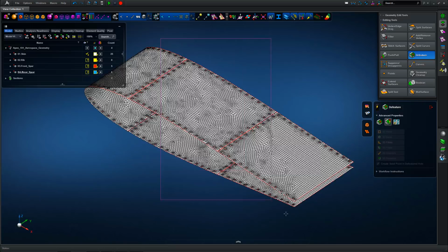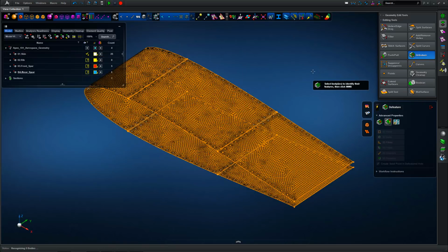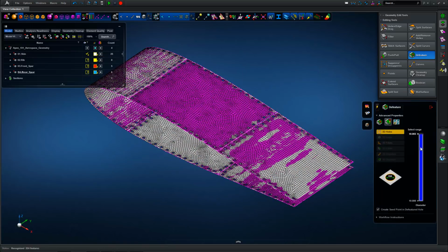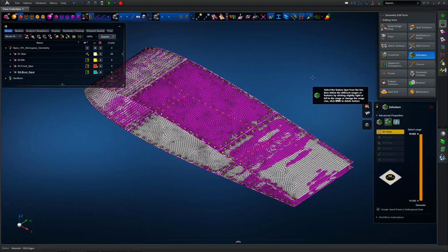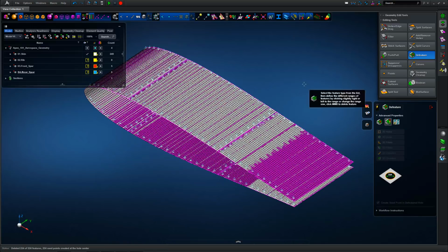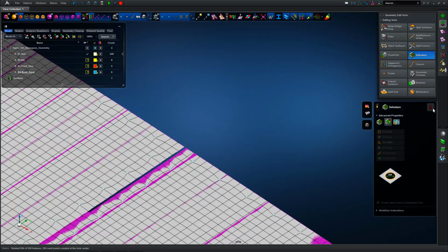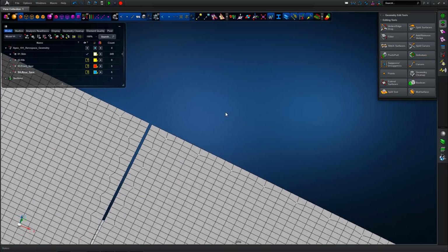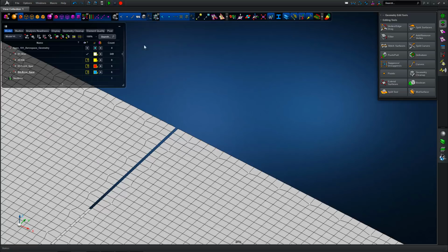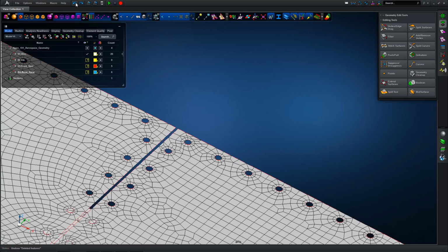Obviously not in this example, but a quick defeature shows that we now have very regular surfaces, and the hard nodes defined at hole centers. We can see that we've got a near perfect quad mesh for the whole of the surface structure.